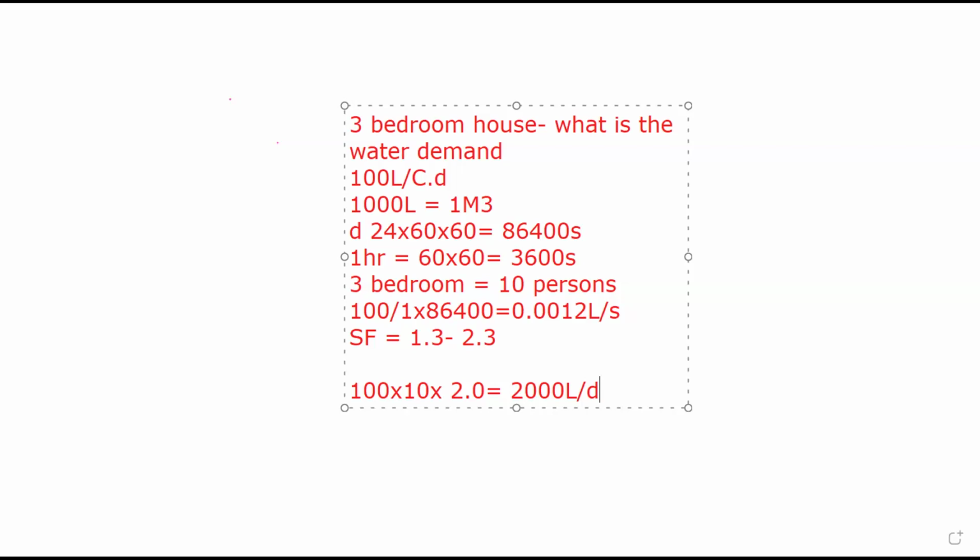Nobody uses the university master plan. If you use the university master plan and the university says in 50 years we're going to have 10 hostels, but now we are building only 2 hostels, a good designer will provide pipe for 10 hostels. All you need to do is to plug it.